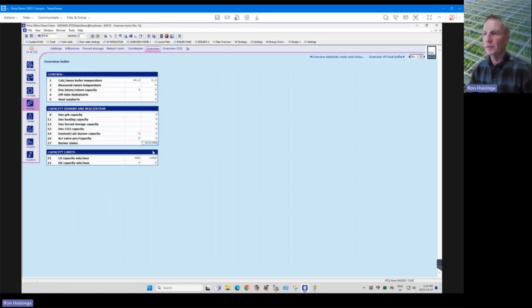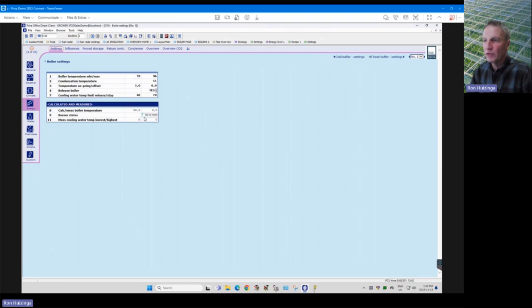A new line pops up. It says cooling water. Basically, it says that the cool water, cold being 42, normally 46, coming in the back of the boiler is too warm, and it can't cool the boiler. And then the boiler's going to shut off.